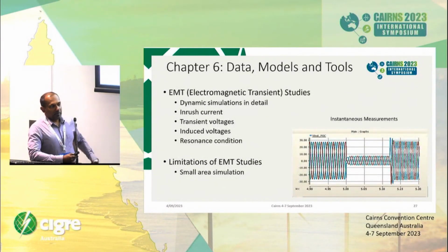So that's why the more detailed EMT studies may be required. They produce, as you see on the right side, the instantaneous waveform with more detail. Obviously, you will see more information like inrush currents, transient voltages, and other things. But again, the restriction is that it's more detailed, and you may not be able to cover very large areas. But with recent developments in EMT simulation, when it comes to black start, which is relatively small, it's now almost possible to do any kind of study in an EMT background. But that was not the case 5 years ago.